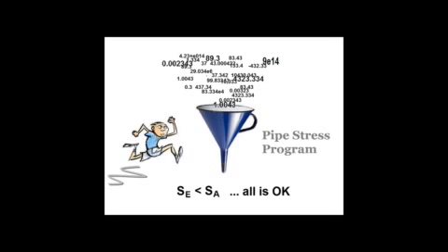Most of the time, you want to put the numbers in, crunch the numbers in your pipe stress program, see that your stresses are okay, and move on to the next problem. Now, people are saying I'm crazy. Well, the reason most of you want to do this is because you're experienced pipe stress engineers. And an experienced pipe stress engineer doesn't use the analysis to tell him if the system is okay or not. He uses his judgment. He uses the analysis to verify his judgment, because it's a system he's seen 100 times. For those problems, he can put them in, he gets the answer he expects, and on he goes. That's the way most pipe stress should be run today.